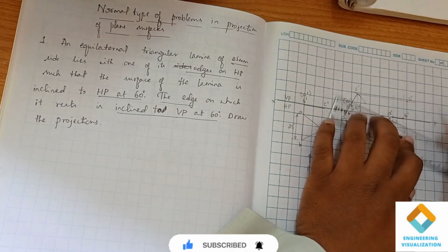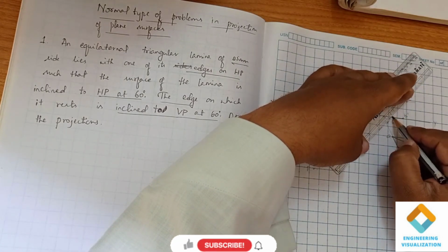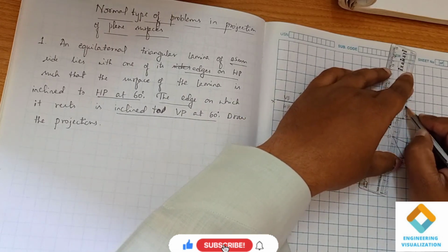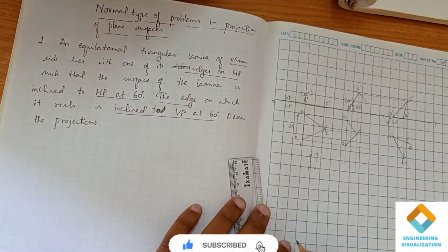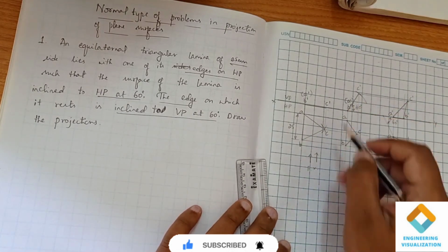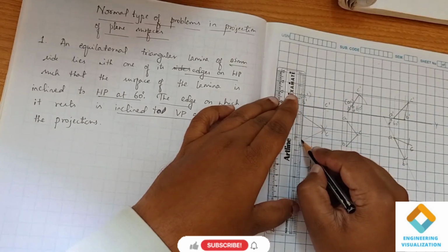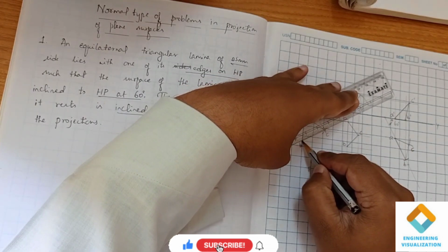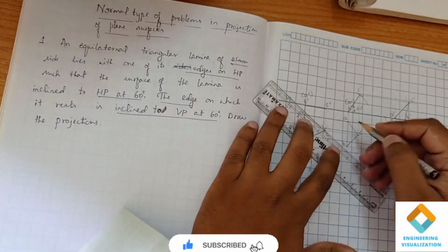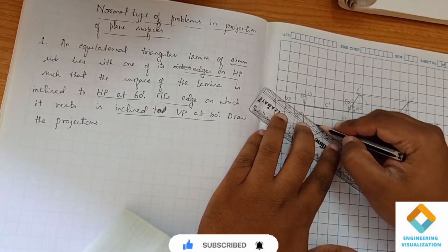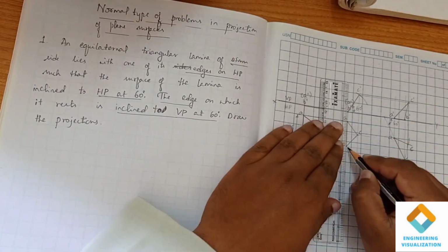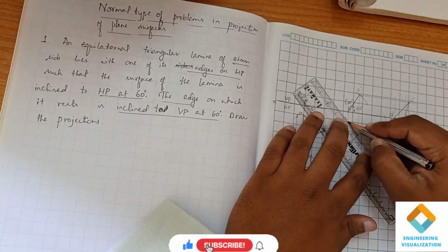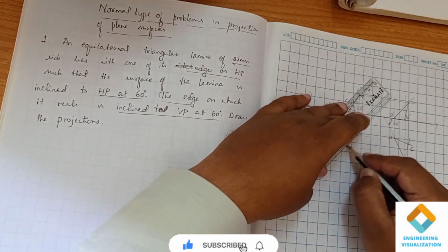AB we have joined. Now from A to C dash and B to C dash, we have drawn. You see that. These views need to be darker, drawn with thick lines, and projection lines have to be thin lines. The actual views have to be thick lines. So now you understood, right? So it is like this.